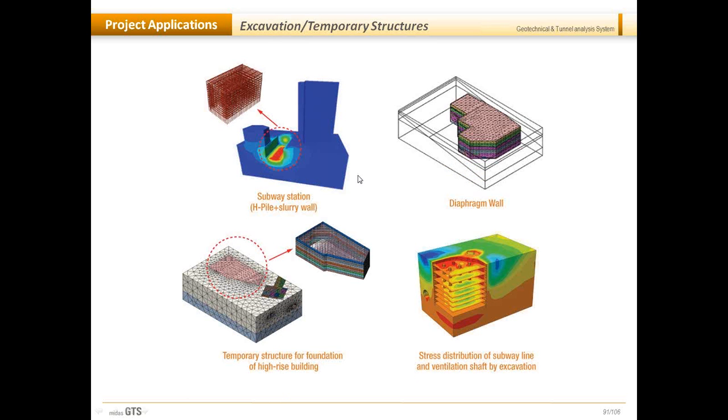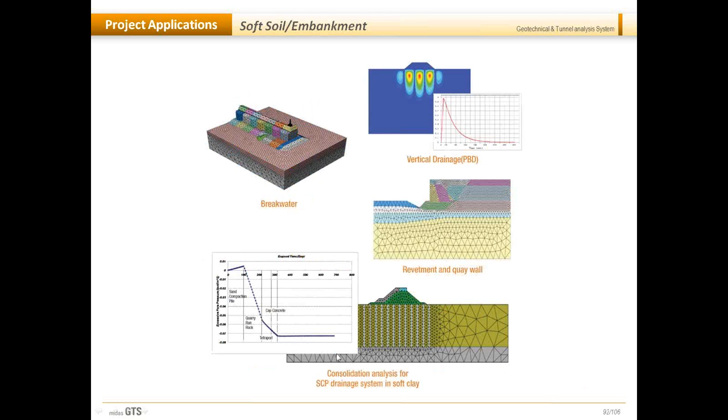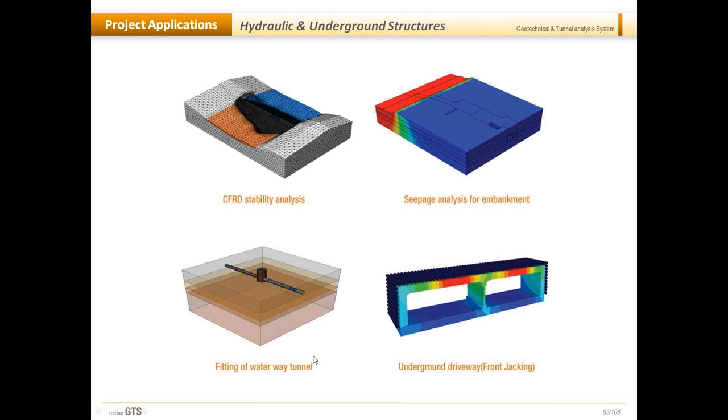Excavation and temporary structures for the subway station, or if you want to add the diaphragm wall, temporary structures for the foundation of high-rise buildings, the stress distribution for the subway line, soft soil and embankment analysis, vertical drainage, consolidation analysis, hydraulic and underground structures.